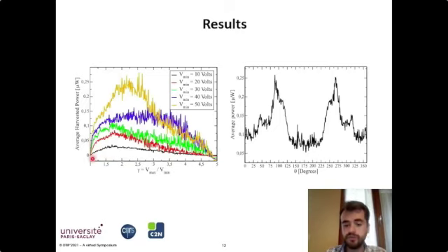And we see the power output. So we see that for gamma equals 2, we have a maximum for almost all values of voltage, and this value corresponds to a Bennett Doubler. So this is potentially the best circuit for this device, where we'll get the most power out.